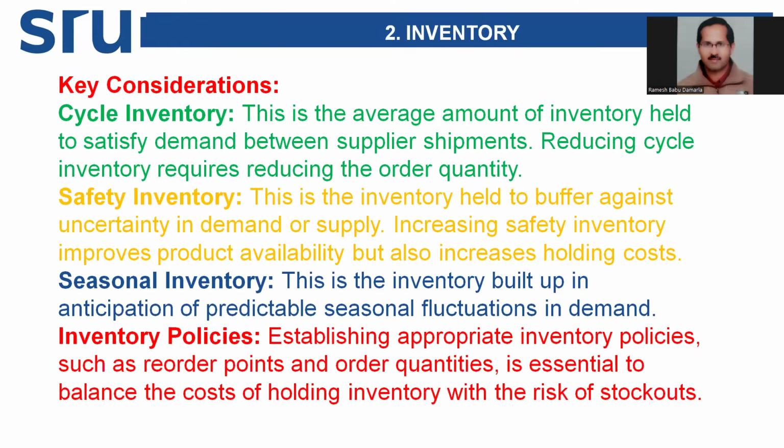So the company may decide to have a safety inventory of, say, 3,000. Now our 10 days requirement is 10,000. So we'll have 13,000 stock on day 0. That means material received from the raw material suppliers, 10,000 numbers, and 3,000 dead stock is already there. So total 13,000. Next 10 days, every day 1,000 we use. And if the supplier cycle time is 3 days, we place the order on the 7th day. On the 10th day, we receive the new 10,000 lot again.